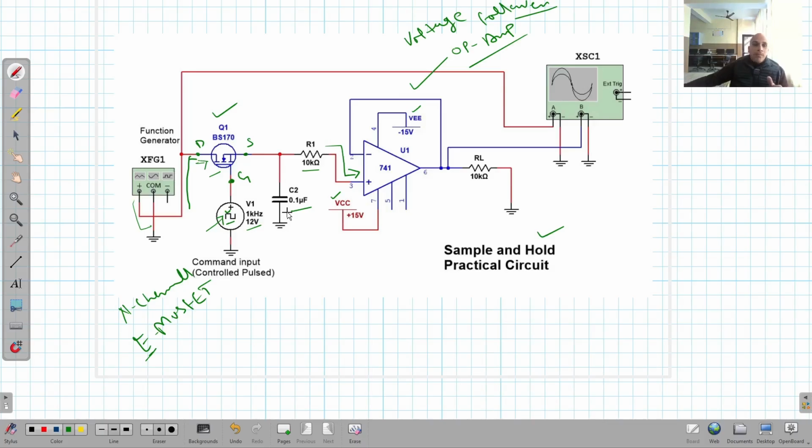So whatever sample was taken during this time when the current was flowing, that sample will be held in the capacitor, and the same is applied here, right? Here I am saying that the same amount of the sample will be held by the capacitor, but in reality the capacitor will discharge very slowly, right? So we are ignoring that. We are taking the ideal situation that the capacitor is going to hold the entire voltage, right? Then after, what will happen?